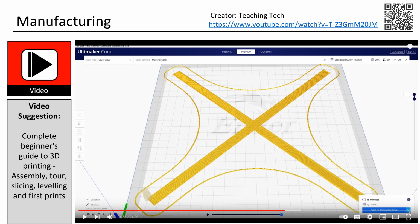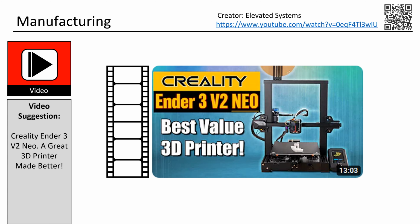Here you see a demo print that is done to check the leveling of the bed. If the print is not good, then one has to adjust the corner where the layer is too thick or too thin. If you want to buy a new 3D printer, I would recommend the Ender 3 V2 Neo.